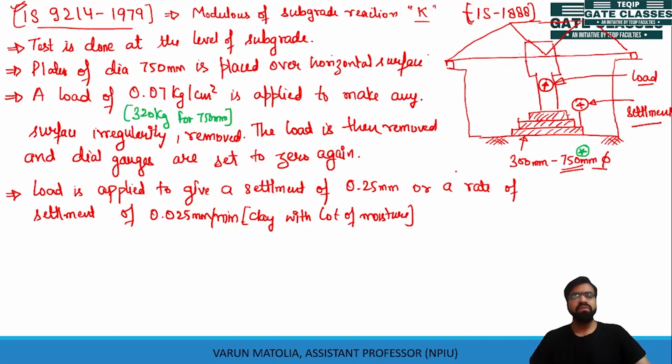Now the load is noted at a level of 0.25 mm. This process is continued till the settlement is 1.75 mm.